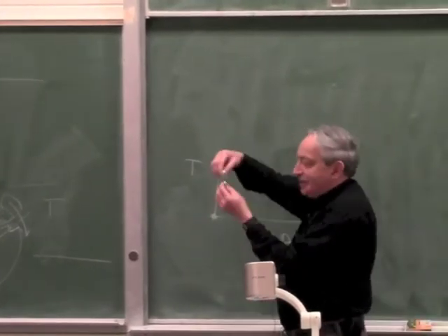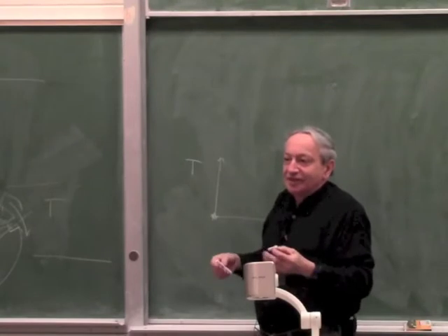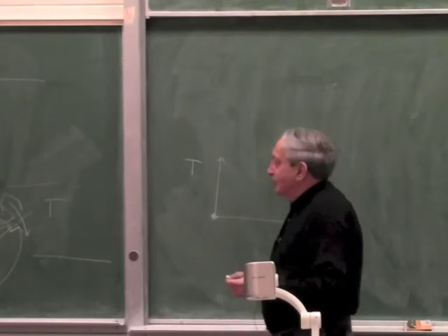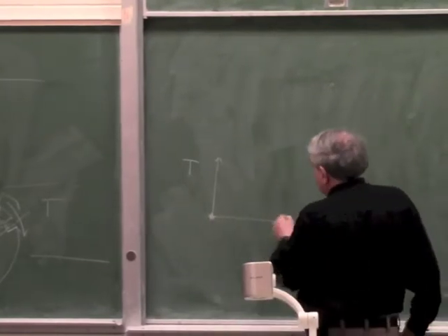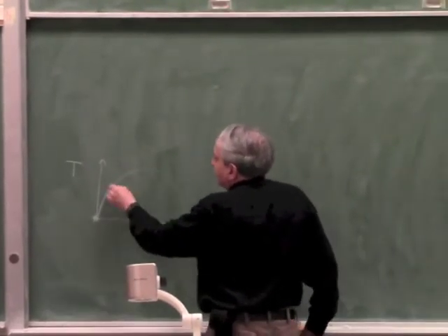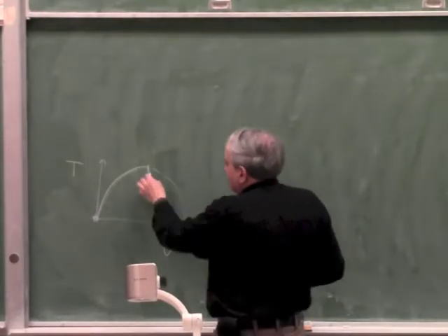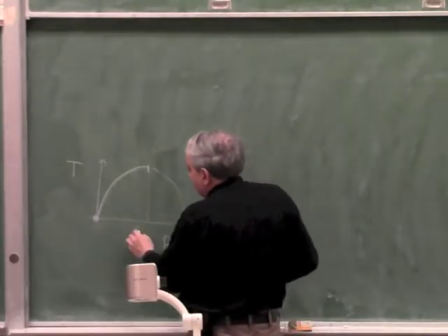Because if the poles are aligned, a little bit of movement doesn't change the flux. You don't change the flux, you don't generate the force. So it's 0 here, 0 here, and it turns out it's symmetric. But you can only use this part, because here it collapses, it can snap over. So you can really only use power angle from 0 to 90 degrees.